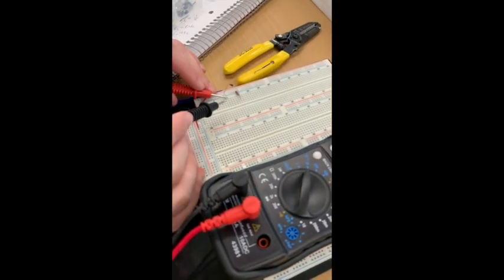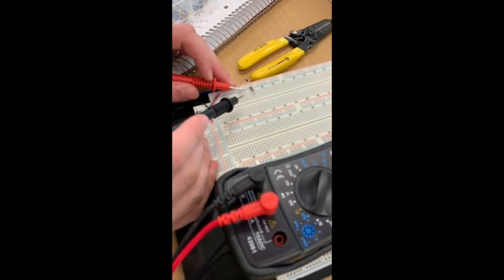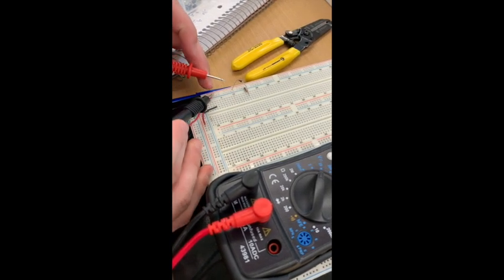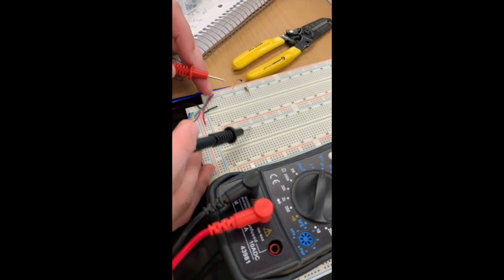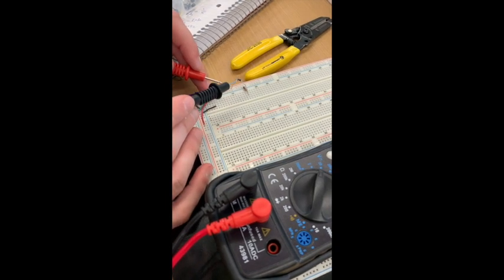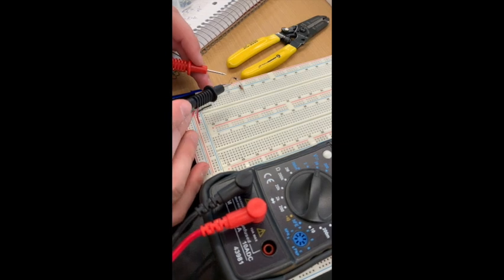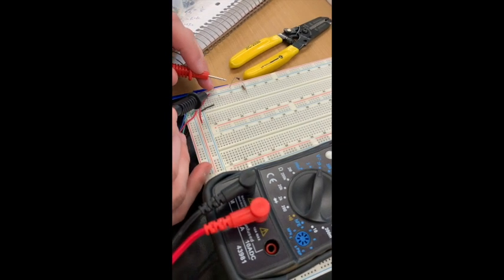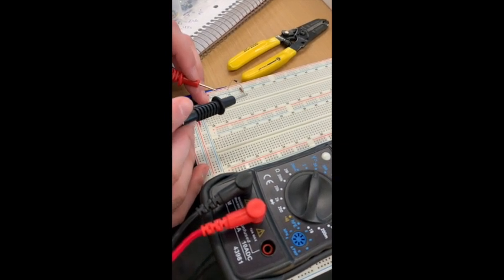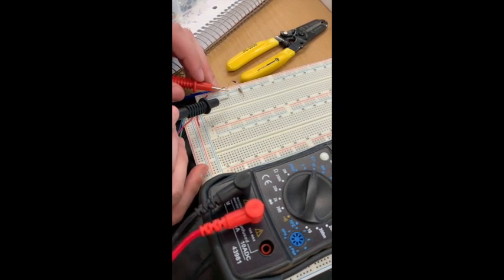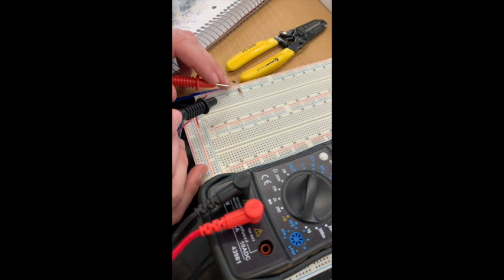Hello, we have the circuit for part A. We have a diode in series with a 1 kilo ohm resistor and a constant voltage supply from the Digilent. This circuit operates based on the principle that the diode will act as an open circuit until a certain threshold voltage has been reached, which we find is about 0.7, 0.6, and I'll show you that in the graph. But I'll show you working now.